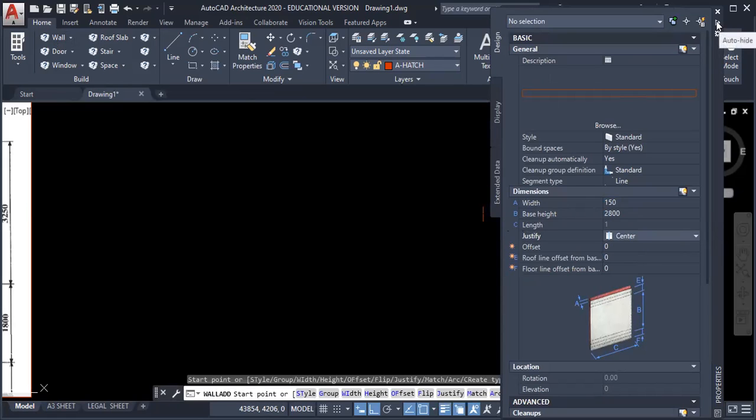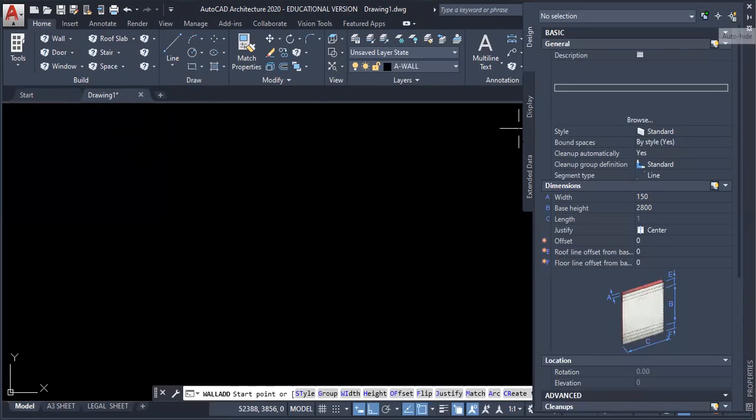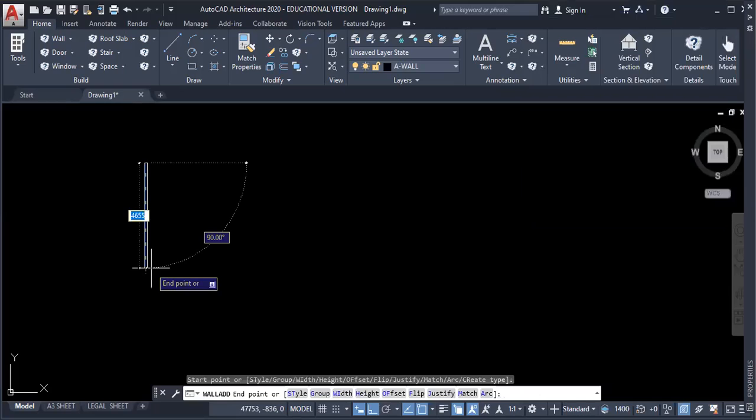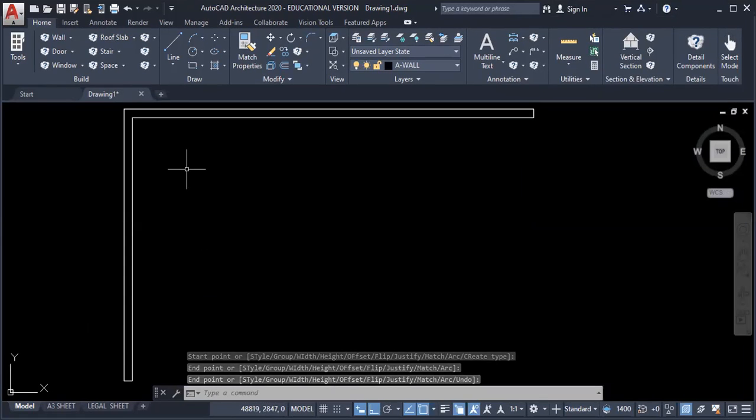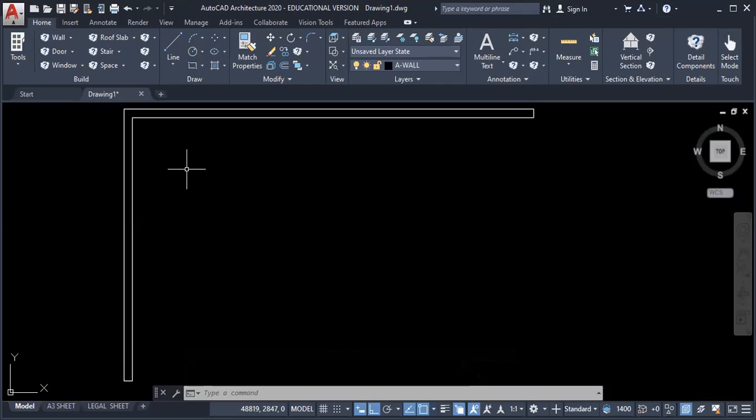Once I've done this, my next step is to ensure that orthogonal mode is on. Click here. Then I'm going to enter, draw a wall. I won't be drawing the entire building per se, so I'm using that as my one wall. Spacebar to reactivate wall, and I click here and bring this out a suitable distance. Next, I'm going to offset this wall to the required distance.